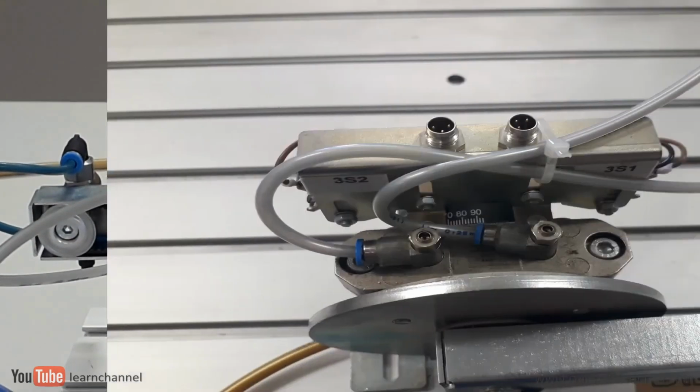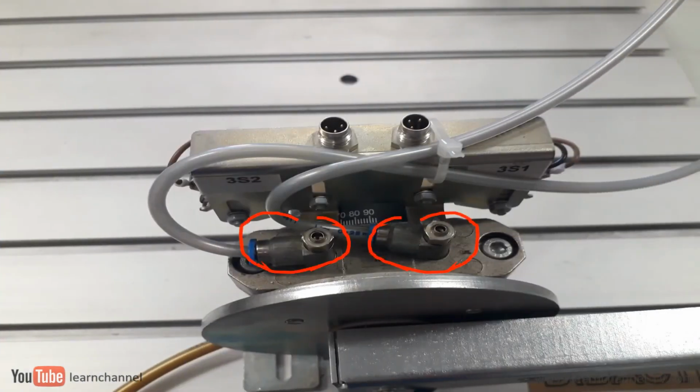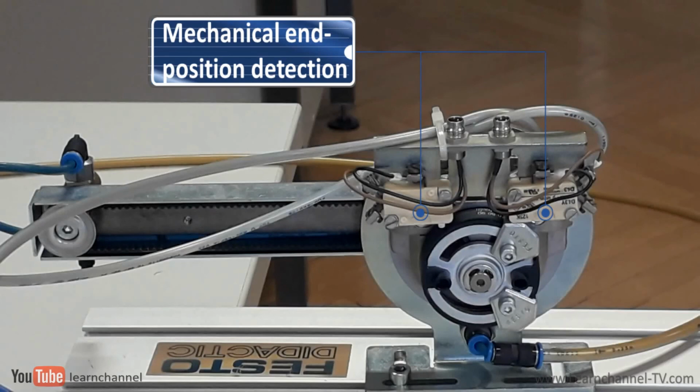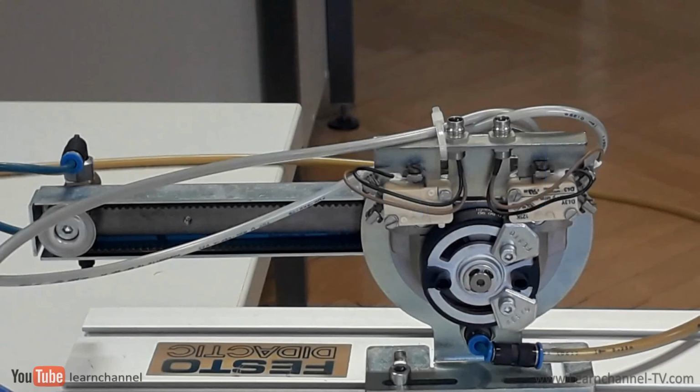This type of rotary cylinder uses external methods to limit the rotation or to cushion the load. The end position of our cylinder here is detected mechanically. Compared to the rack and pinion cylinder, vane actuators are compact in size and less expensive, but the cycle life is limited by the wear of the vane seals. Also, friction caused by the vane seals and leakage over these vanes result in less efficiency.